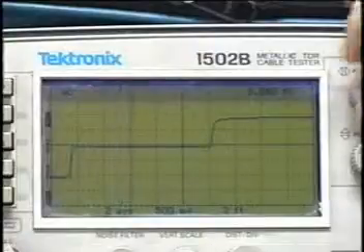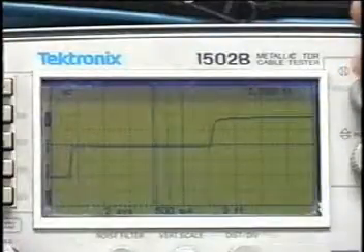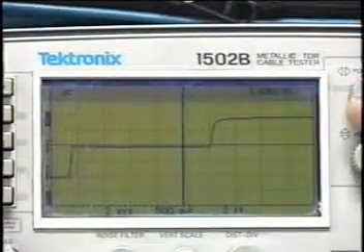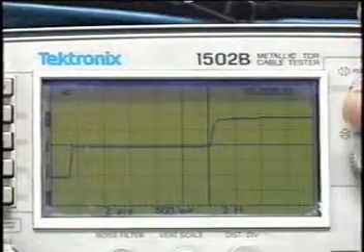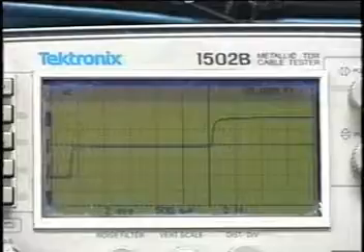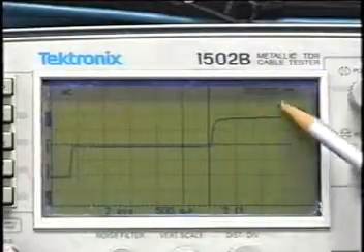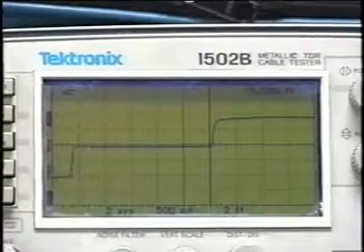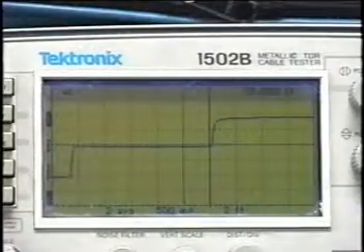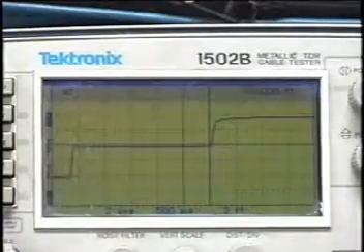Place the TDR's cursor on the leading edge of the reflected pulse, and the distance along the cable to that reflection is displayed in the window. A good cable will show a reflection only at its termination, while a bad cable will show a reflection before its endpoint. Again, make sure you know the cable's length, impedance, and VP to ensure correct readings.